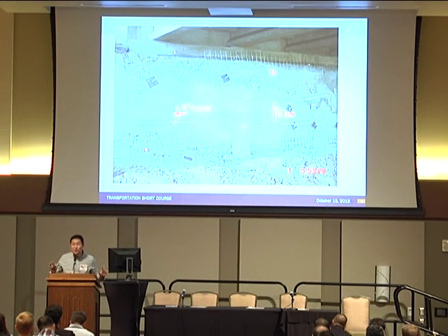It has a lot of issues in this picture, but if you see significant bar length sticking out, first you need to suspect the soil nail length. So make sure that you have the soil nail length called out in the contract plan.